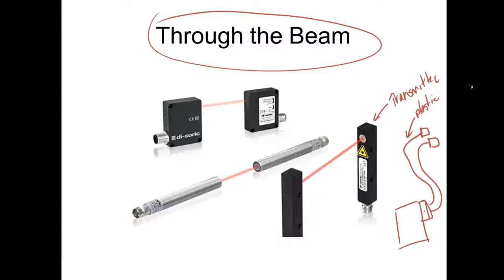It all depends on the core size and what type of fiber you got. It depends on how you go through the cladding and the thickness of the cladding. There's a little bit that deals with the critical angle, but that's something that's specified when you buy the conductor. So you can't run them in loops and stuff like that. You can't bend it a real long way, or you'll cause the light to come out the side.